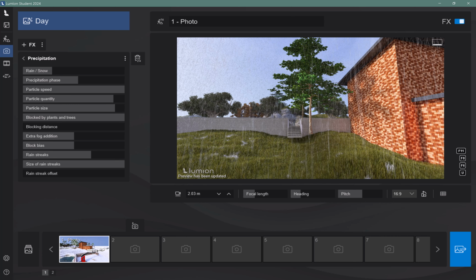You just need to plan ahead in your model, decide what is going to look hardscape and what things are going to look more naturalistic. Then try your best to create the hardscape items in Revit, and the more naturalistic items, you'd create those in Lumion.